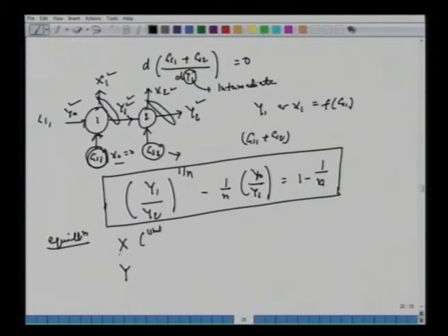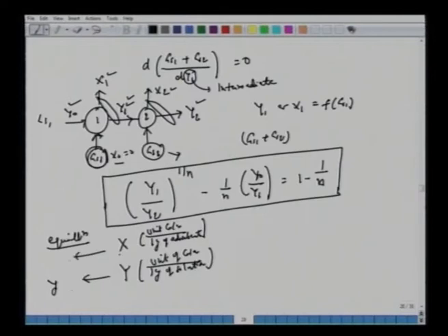We had certain units of color per kg of adsorbent, which is charcoal here, and here some units of color per kg of solution. Again, as per the conventions we should have been working with small y and capital X, but since it is a very dilute solution, capital X is approximately the same as small x, and capital Y is the same as small y.